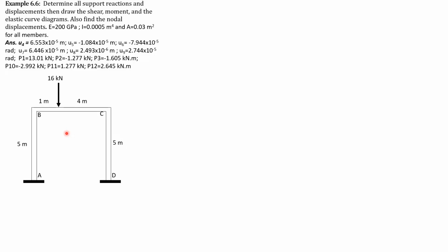So you may make your matrix calculator, or you solve this manually by using Excel in inverting 6 by 6 matrix. You will be forced to invert 6 by 6 matrix because after that, for member forces, you can easily multiply 6 by 1 or 1 by 6 with 6 by 1 matrix, or row matrix with column matrix.